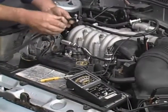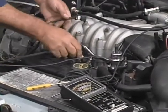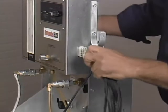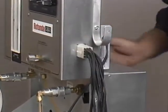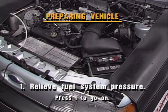Next, install the injector tester harness, matching the harness connector numbers with the vehicle cylinder numbers. Connect the harness to the tester at the white connector on the end of the tester. Now let's go through preparing the vehicle once more. Press 1 on the controller to go on.